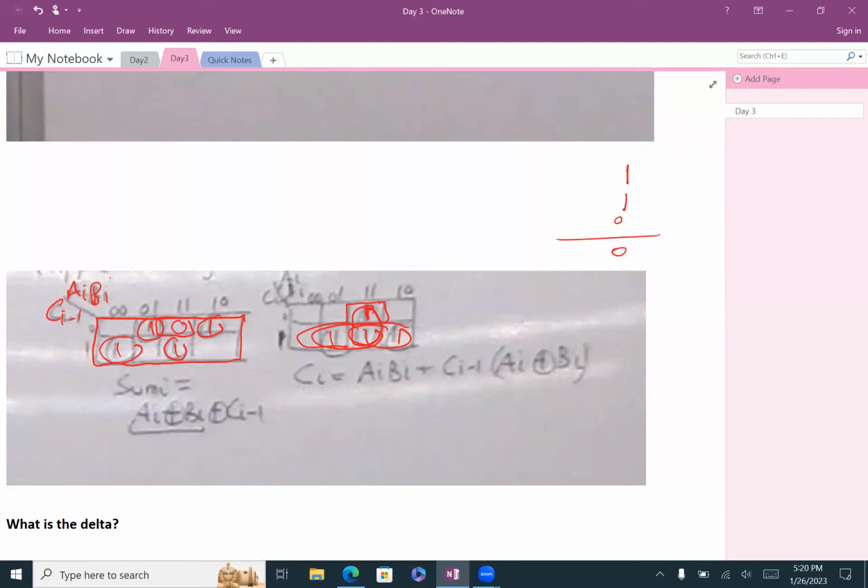So again, that's why we call it carry look ahead, or the method is called look ahead approach. Since that's an adder and we're trying to find the carry using the look ahead approach, to find the answer quicker, the technique here is we're trying to eliminate the carry. So stage one should not rely on C0. If you can find the carry quicker, then that will speed up our process.